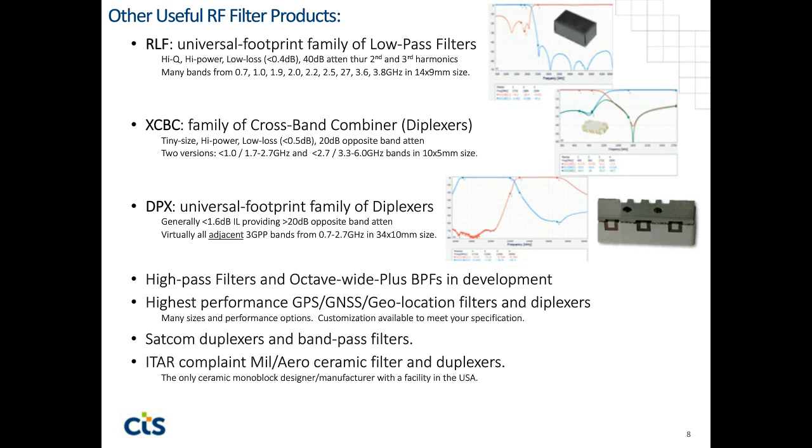What ends up being critically important is the peak modulated power, since in many cases the power is going straight from a PA on a transmit side into the filter.